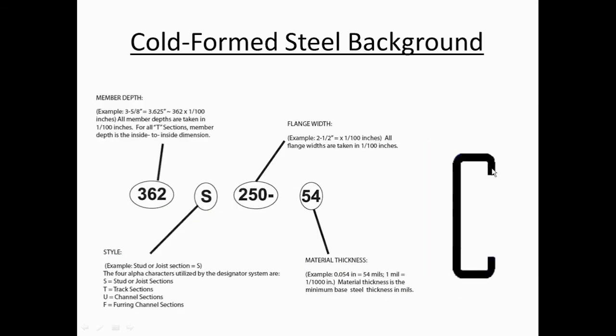This C is the standard profile that's used in cold-formed steel framing, and I want to take a moment and walk through what I call the anatomy of a stud. By that I mean, what are the various elements and what do they do to help this profile function as a stud? First, we have to realize that forming and shaping adds greatly to the stiffness of a profile.